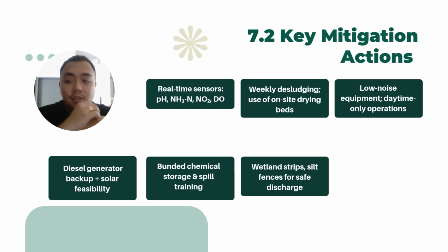To minimize noise, low-decibel pumps and daytime-only operations are suggested. We also included diesel generators for backup power, bunded chemical storage, and staff safety training. Lastly, to manage water discharge to land, vegetative filter strips and sediment traps are planned.